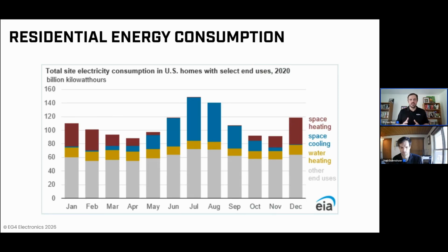And again, this kind of reinforces what we talked about previously, that climate control is a huge portion of where the energy is being deployed in homes in the US. So having the intelligent control of that device is going to impact the longevity of that energy storage system significantly. It can sometimes increase the off-grid runtime of a solution by 30 to 40% just by that intelligent load control.